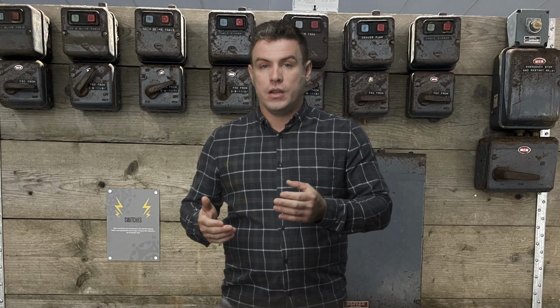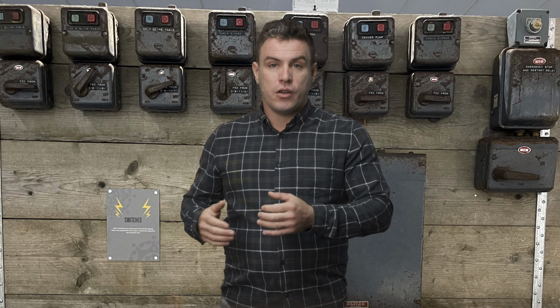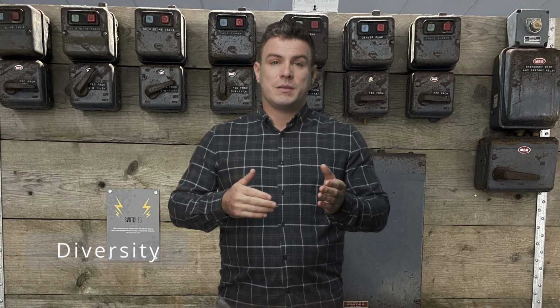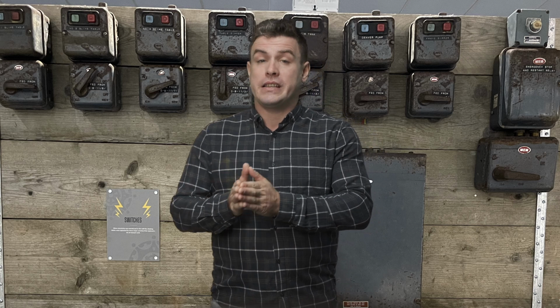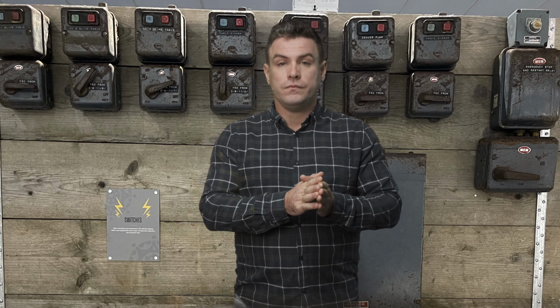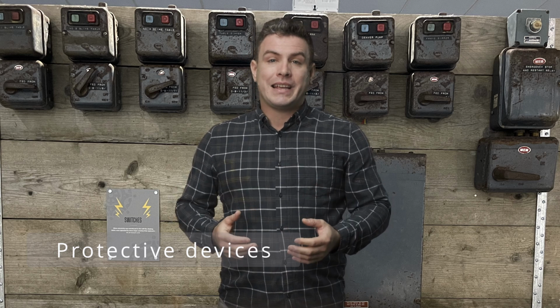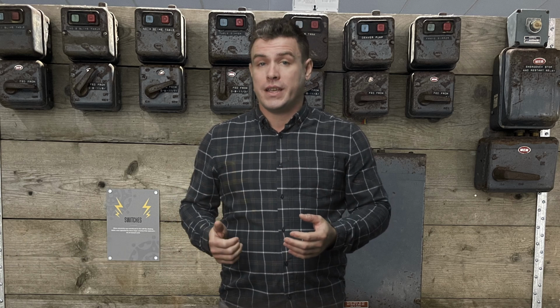For example, we spread the lights across the circuit with a ring on another. Diversity was mentioned. This considers the spreading of loads, taking into account how likely loads are to be active at the same time.